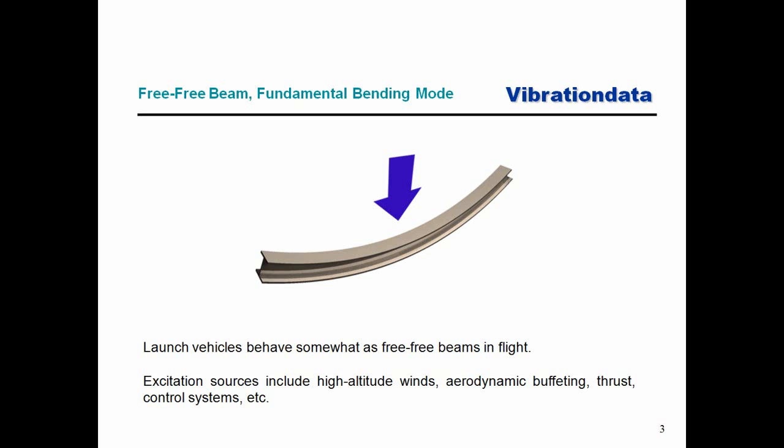However, just recall that these are guided vehicles, and there are inertial navigation systems on board these vehicles, and typically they would have 3 translational sensors and 3 rotational sensors. Those could be gyros, for example. And that set of 6 sensors, the intention is that they will measure the rigid body acceleration of the vehicle. However, these launch vehicles also undergo elastic body vibration as well.